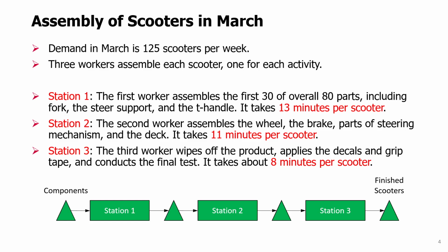Maybe some activities have to be done very carefully in order not to introduce quality problems. So maybe over time, when the time of each worker's activity was measured, they found out it takes actually much more on station 1 than station 2, and then even more than on station 3, right? So this was not by intention. This might be basically the result of some initial division.